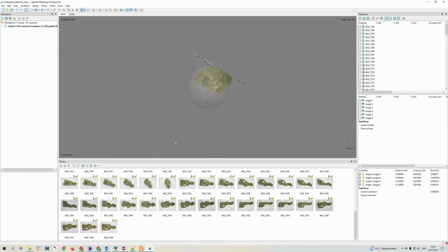If you're unsure whether a certain intermediate state of the calculation would be needed later, these steps can be duplicated. In Metashape, these intermediate steps are called chunks. Duplicate saves a work step that can be later accessed and started from again.